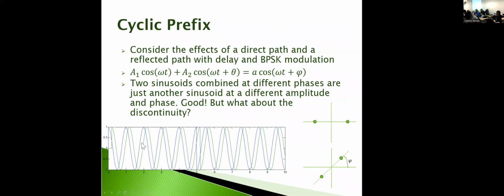So this looks like a BPSK type signal, or binary antipodal signaling, right? And at this time instance, I'm going to flip the modulation, because now I've got a symbol coming in that's supposed to be a minus instead of a plus, right? So then we have this near instantaneous switch in phase, and then we've got another few cycles filling up that symbol, right?